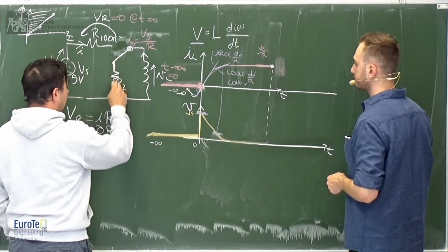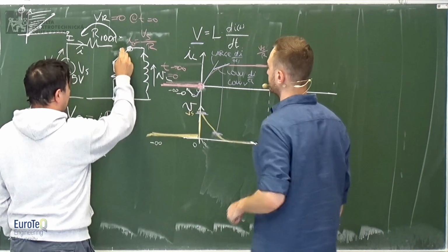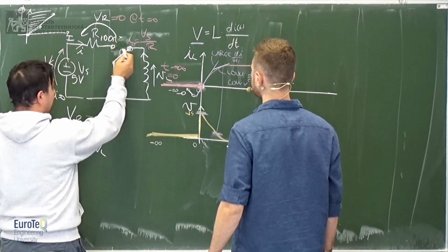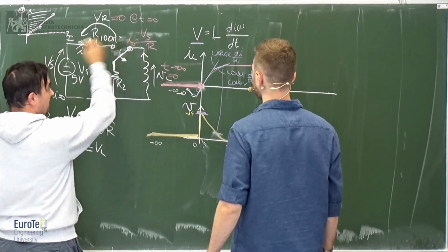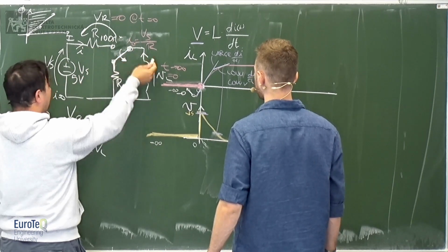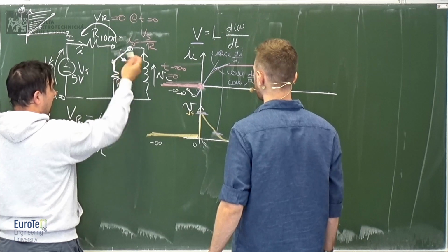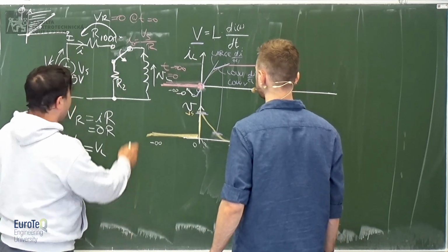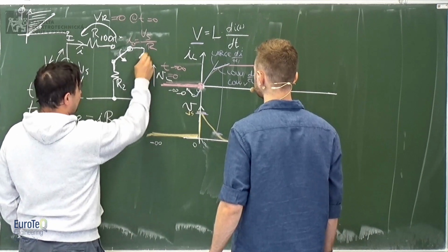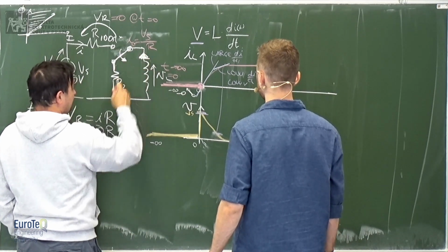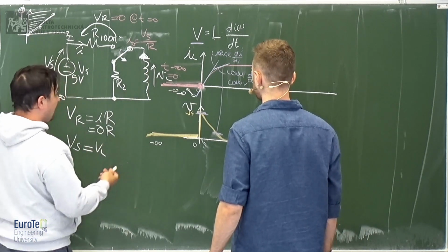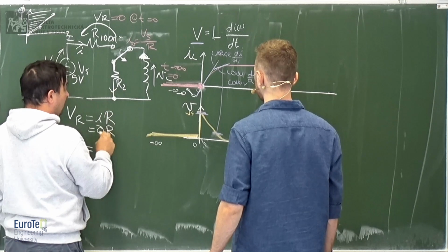Oh, there's another resistor. I didn't see it. Suddenly I stop the current flowing in this main circuit, and I turn it on this circuit. The current will continue to flow in this direction, but now the voltage is not 0 anymore, because the current will flow through R2.